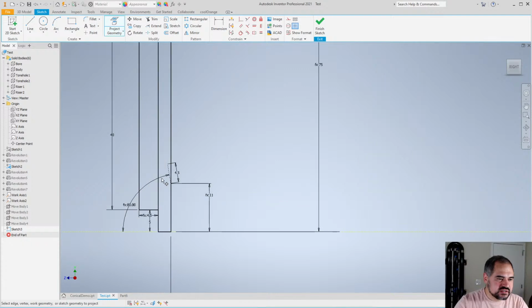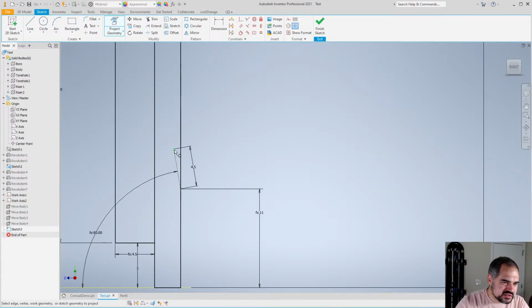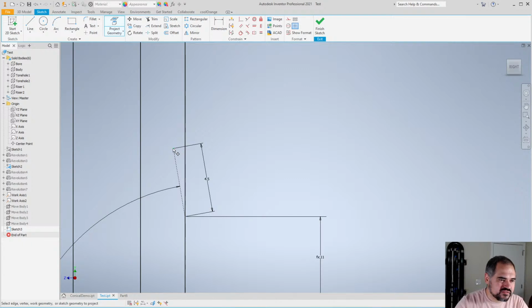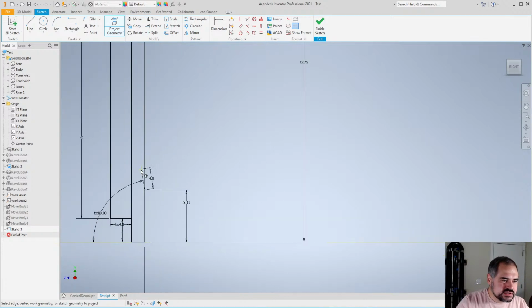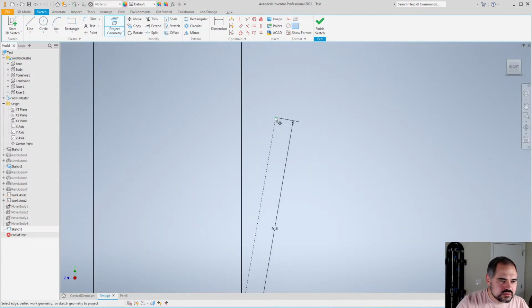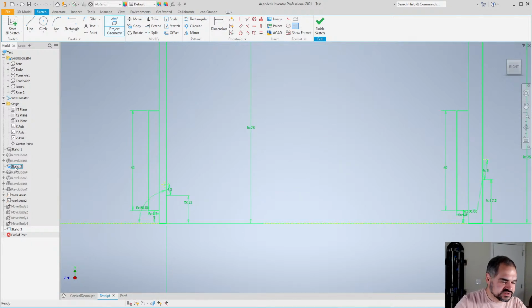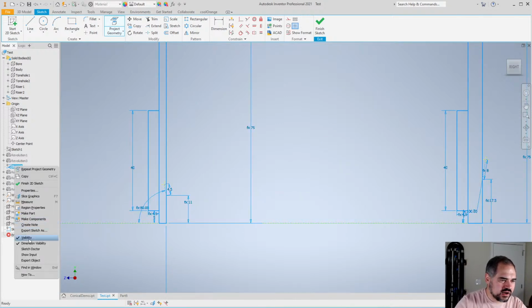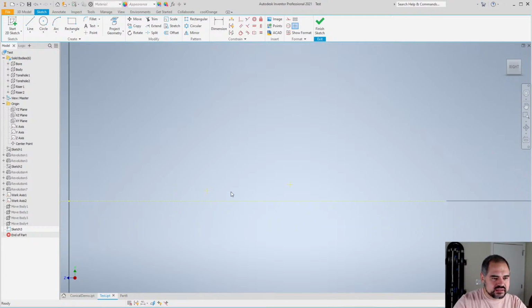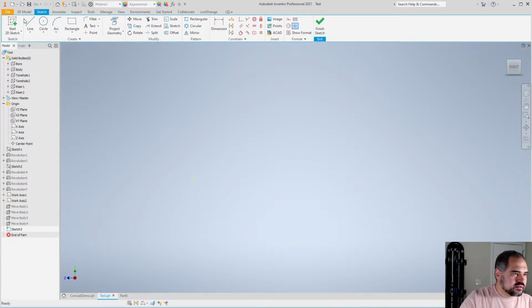And the only thing I need is this point here, because this point is going to be the center of our facing, because it's the center of the exterior of the hole after we have rotated the hole. So project that point, and project that point from our tone hole sketch, and now we can turn off visibility, and there we go.